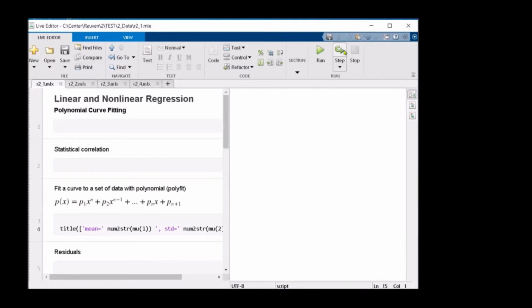Okay, we will start from the regression analysis of the data. Regression is a method of estimating the relationship between variables, for example, between the input and output, or different variables. We can use linear regression, nonlinear regression, and Matlab itself has several commands for this. Most importantly, there is the Curve Fitting Toolbox inside Matlab that can also help us to do it.